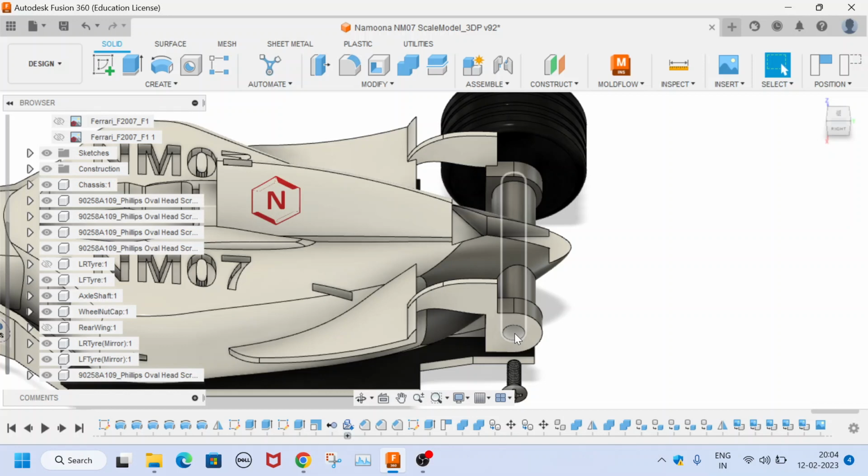and the surface finish is at least 3.2 to 6.4 micrometers in surface roughness terms, so that the wheel will have very little friction when it is rolling on the floor or when you are trying to play with it.